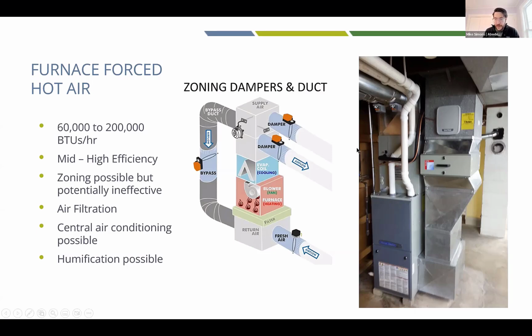Okay, so I can see that this has an insulated refrigerant line and an uninsulated refrigerant line, which makes me think that it's an AC and not a heat pump. But do know that this box over here, that's the heat pump solution from all US manufacturers. It's really just a coil that sits on top of a fossil fuel-based furnace.